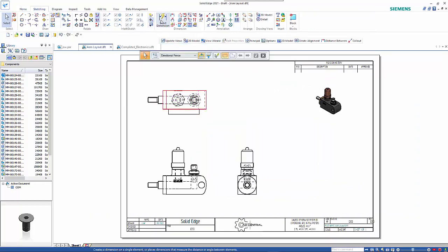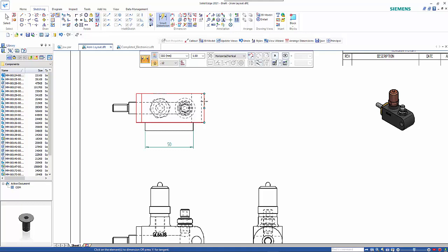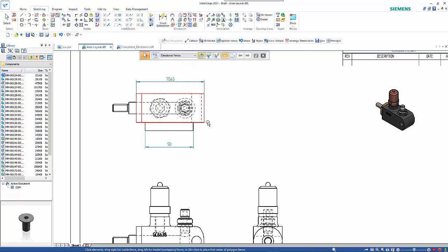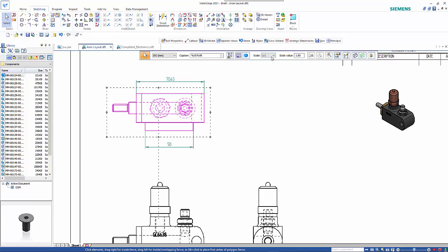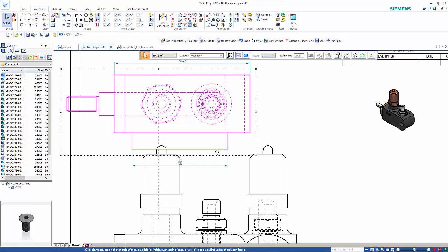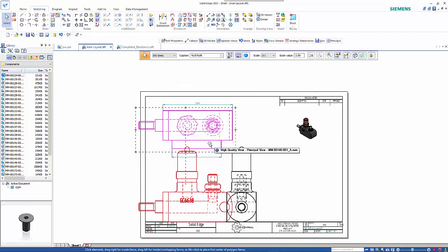So if you add dimensions onto something, this could be for anything, you know, like a post-production type exercise, for example. So you can see that we are fixed to that size. So if we then come back in here and change the view scale, that value there stays exactly the same, whereas if we draw on the drawing sheet, it won't.